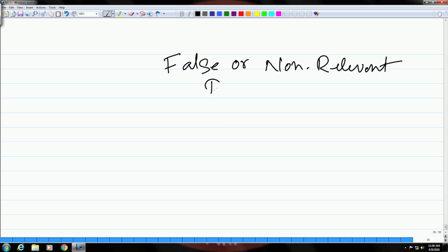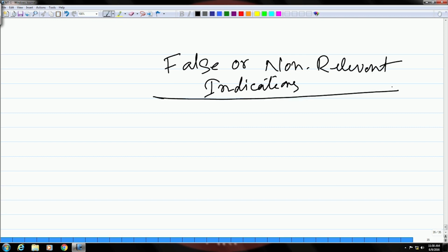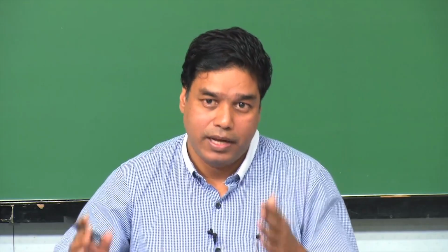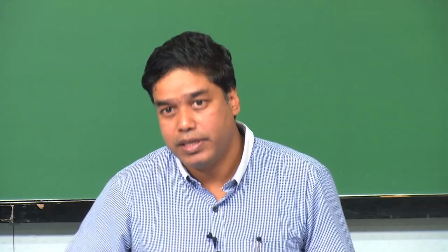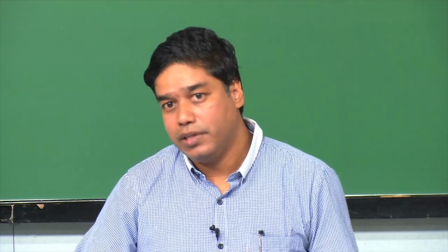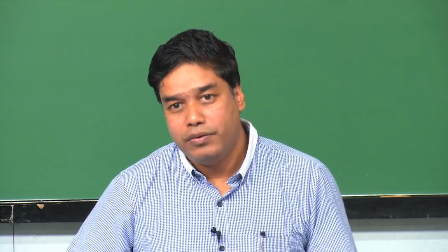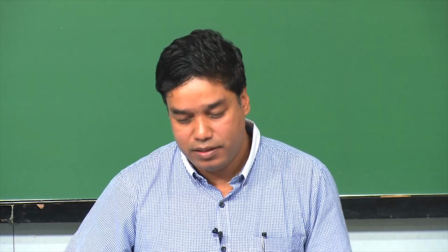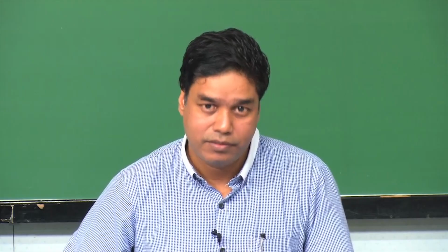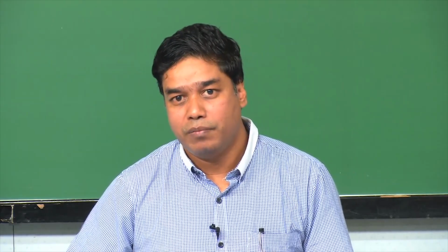Which could arise due to various reasons. This may look like a defect, it may give an impression of a defect, but it may not be a defect. These false or non-relevant indications may look like a defect on the surface, but actually they may not be. So, while doing NDT, you should always be aware of these non-relevant indications, so that you do not make a false call.